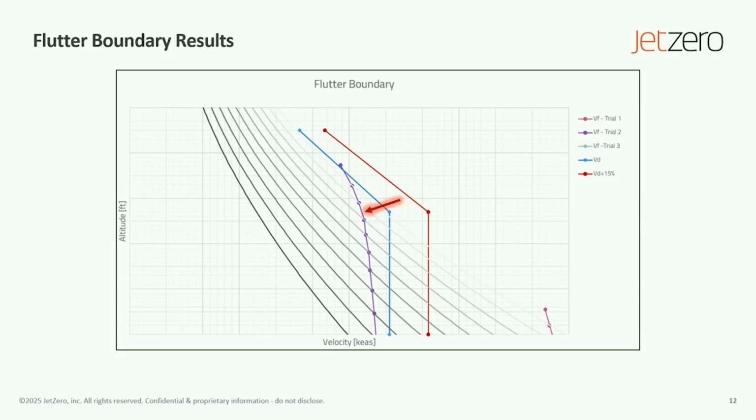But we really need something that can give us a better stiffness estimate. So we have to rethink, like, what should we do? We ended up doing the SOL 200 method, and constrained the optimization sizing to pass the flutter requirement, and also maintain the lowest weight.